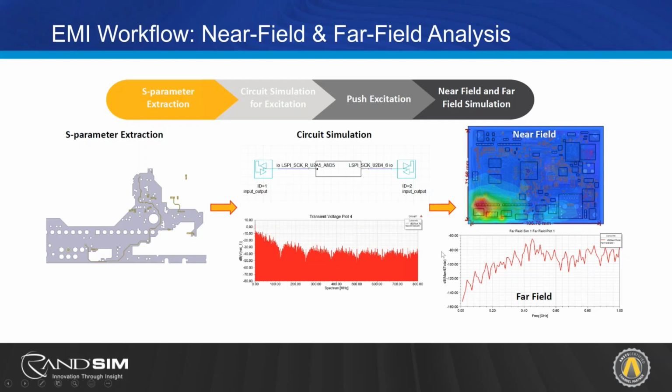And you can effectively get an idea of how high or how near the compliance level you could be hitting based off of what your far field data is showing for a specific frequency. So here we have a peak right around 450 megahertz. That looks to be close to a third harmonic of that 150 megahertz. So let's take a deeper dive into how this is all done.